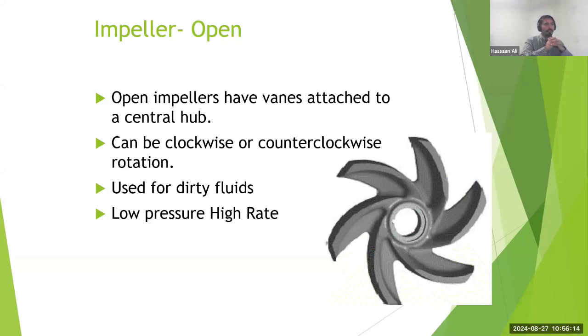One of the cautions I would say is to ensure that you have fluid all the way to the suction of the pump. If the line to the suction of the pump is empty, the pump will not be able to pump, because it's not a self-priming pump. It has to be primed. That means it has to be filled with fluid for it to start operating. So that is one caution I would say when selecting this pump.